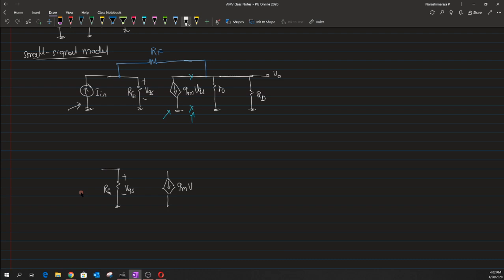Now this dependent source is a current source, and we know that this current always loops. Okay. And we want to extract a current, so the current that is measured will give us the value of this IR. Okay. And the direction has to be in the same direction. So what it really means is that this current has to flow in this loop, and whatever the current that is looping here is measured as the return signal IR.